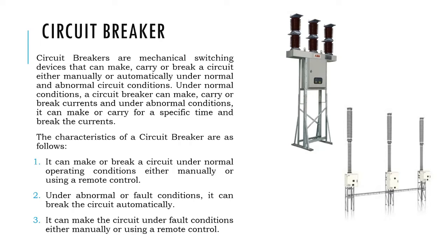The third one is oil. Oil is not used at all now because of leakage and other issues. Next is SF6. Above 33 kV level, all the breakers for the remaining voltage levels are SF6, which is a gas having a high electronegativity.